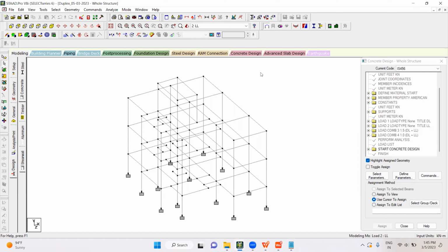consultancy services. So you fix for 3 SBCs, 150, 200, 250, and then 500 kilonewtons load, 750, 1000 kilonewtons load, and then 1250, 1500, 2000, 2500. That's it. There will be hardly 10 types of foundations for different SBCs. That's all. You need to work only 10 times. You don't need to work every time you design.